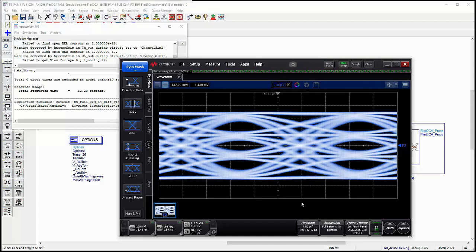By using FlexDCA, you are not only able to do the math functions, but you can also enjoy all the pre-configured measurement capability in FlexDCA. For example, you can go with PAM4 related measurements, where you can do the TDECQ or transition time and linearity and a lot of different things.